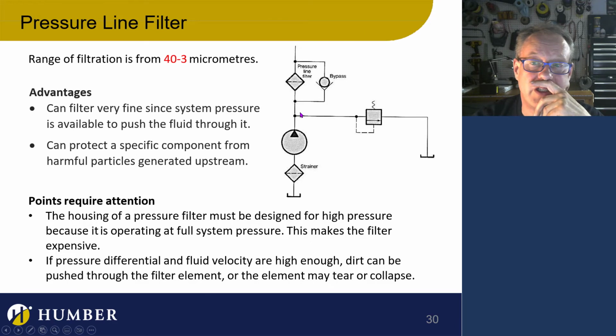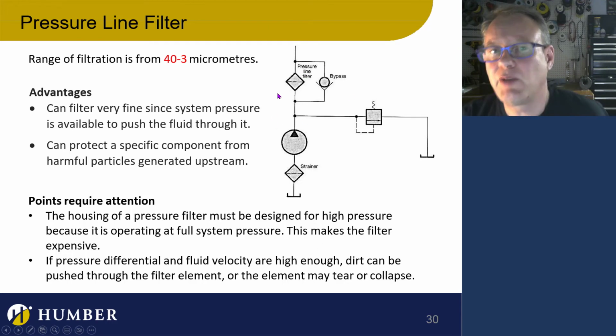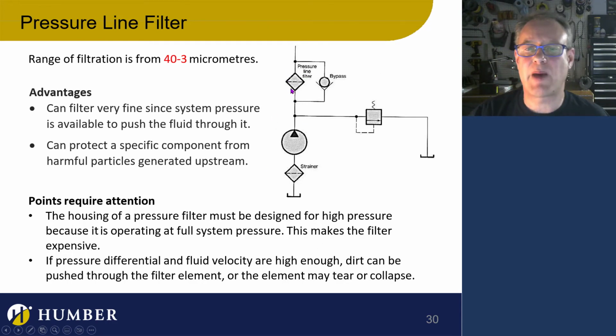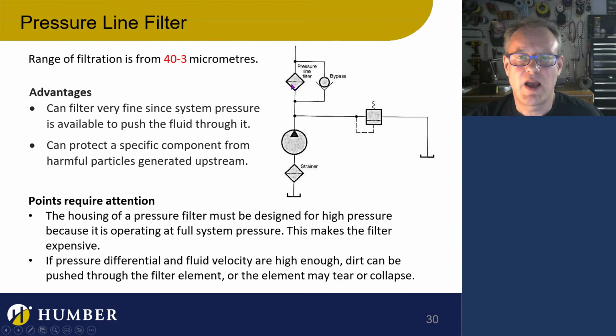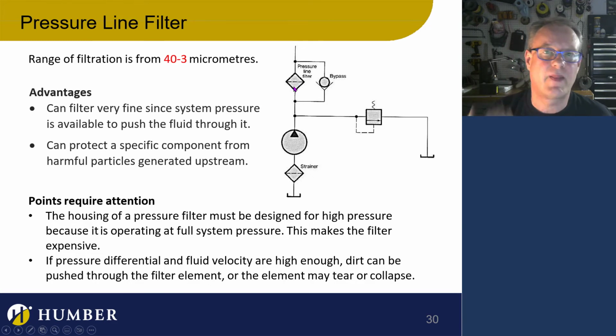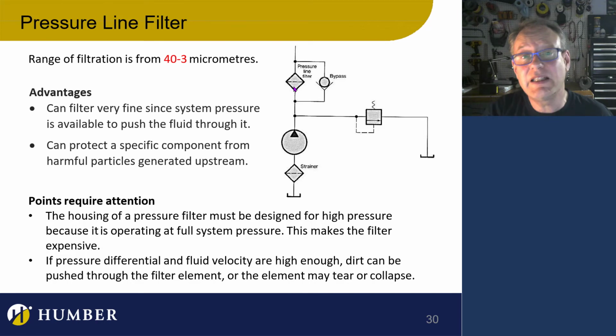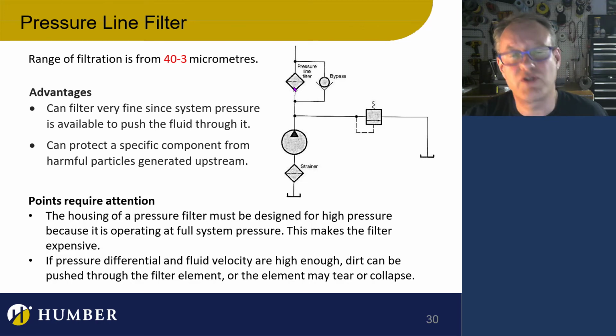There you go. So I think it's important to have this bypass in here. The bypass is important. It'll be inline, inside your filter. You'll have a bypass in the actual filter. But if you don't, you can just put an external bypass on there, and all this is just a check valve. It's certainly good to have, because if that filter gets blocked and you still need to run the equipment for a few cycles, it's important to be able to do that.